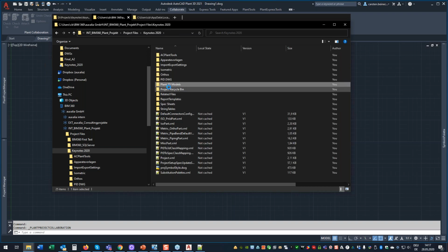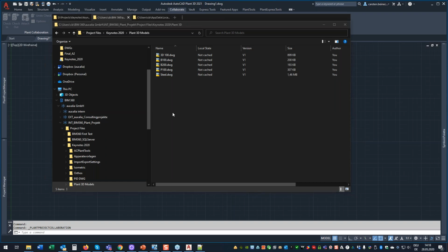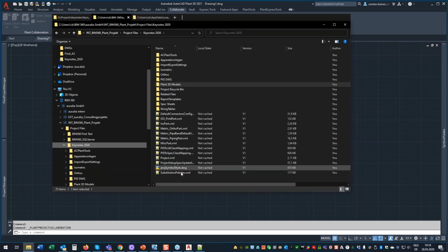So you have the files. You can copy them from there and copy them into another project, but you shall not just use some other file or assume that you just drag and drop them in here and they are showing up in Project Manager, or use a newer file and override it. I highly do not recommend this. But if you want to add other files, Excel sheets or so, and you create some folder here, that's all fine. That's the purpose of the Desktop Connector.